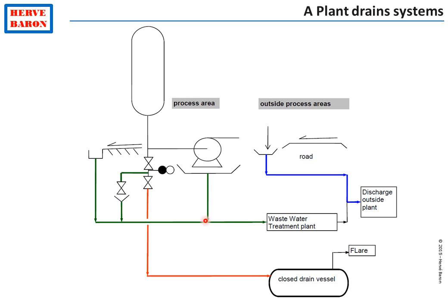The open drain network, shown here in green, collects non-hazardous liquid from process equipment. For example, the water used for the periodic hydrostatic test of the equipment. The open drain network also collects small oil spills that could happen around equipment and are collected in equipment drip pans.